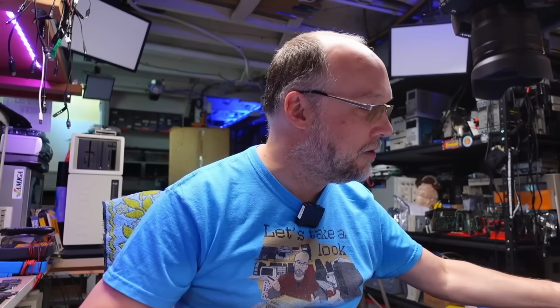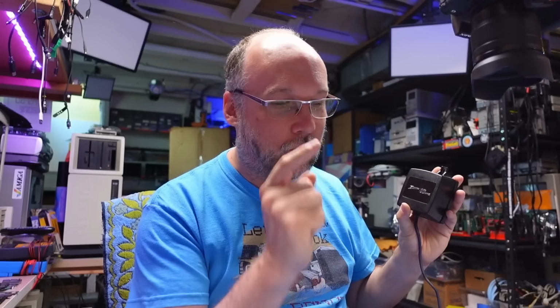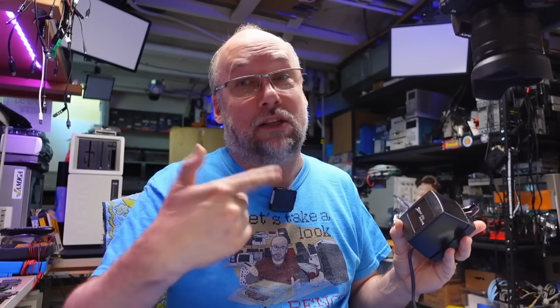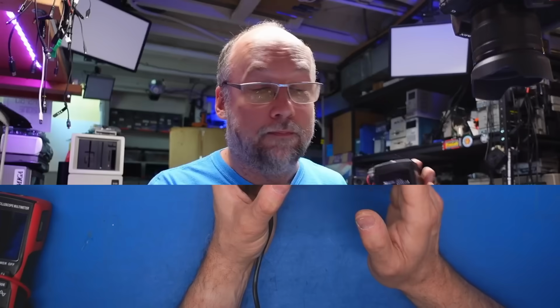And the first thing I want to do is try to work on the power supply, because we know this got damaged when the tantalum shorted. It took this out entirely, and maybe this thing is not running properly because it's not getting the time signature that would be coming from the power supply, because I mentioned I'm pretty sure the clock is probably run off the AC waveform from the line frequency, and it's not going to be seeing that. So maybe the microcontroller just sits there waiting in some kind of a loop, and that's why the system's not booting. So let's try to fix this.